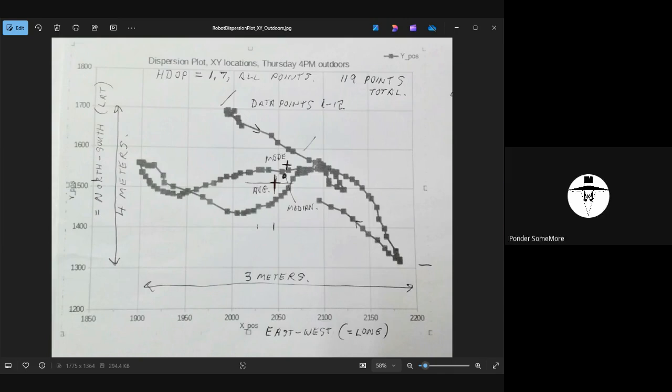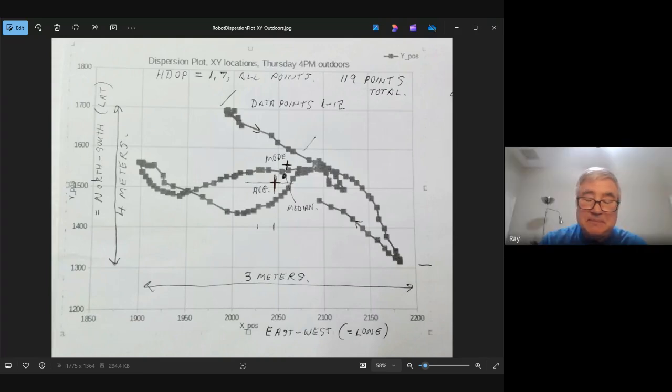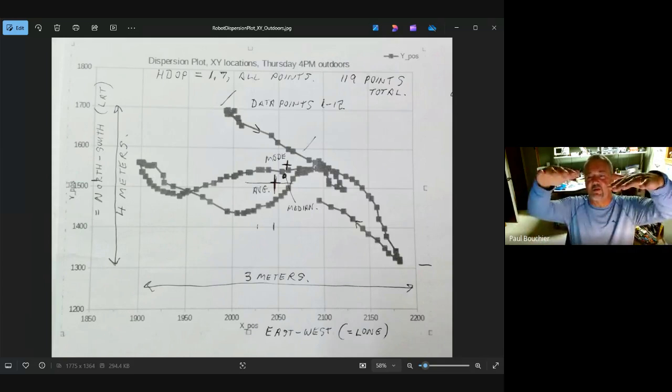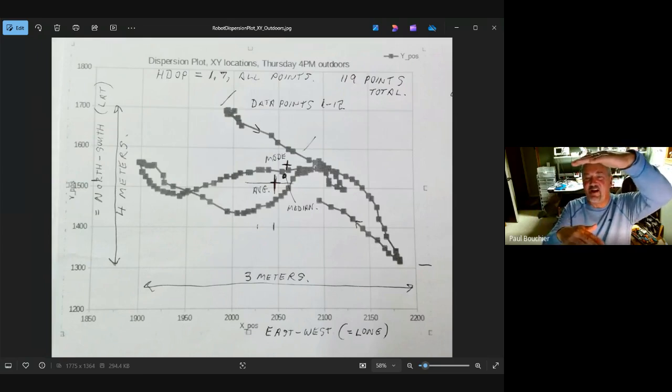In a cell phone, they've got pretty good fusion with other signals like Wi-Fi and cell phone towers that they can stabilize. Yeah. But if you're using RTK, a ground plane is absolutely mandatory, because what it does is prevent the reflection off of the ground from coming back up and hitting the antenna, this much or whatever the antenna height is later than the direct signal.